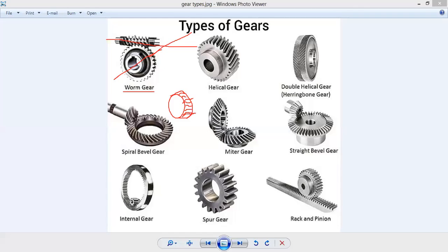Similarly, according to that, the gear on the other shaft will also be used. Either another worm gear can be used, or we can use a screw rod. We can have one worm gear on one shaft and another worm gear on another shaft, where they can mesh like this. Or we can have a worm gear on one shaft and a screw rod on the other shaft like this. If the gear rotates, since the screw present on this rod has a helical shape, it will engage.